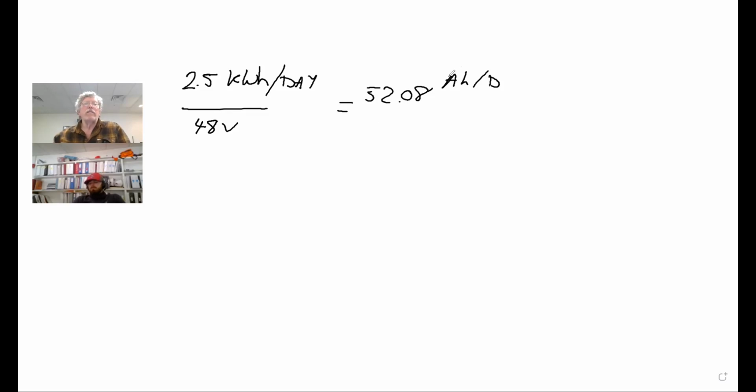So do I want 1 day of autonomy, 2 days of autonomy, 3, half a day, 4 hours? You know, it doesn't have to be a full day. But let's assume we want 2 days of autonomy. That's just something that you're going to have to decide. Well, then we'd be looking at 104 amp hours for our system.